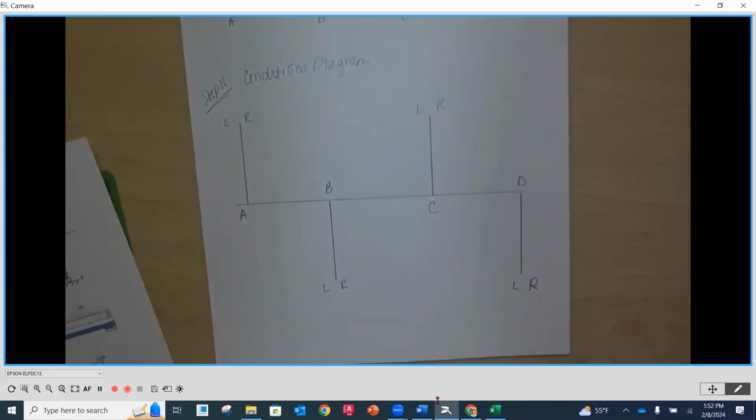So now we're going to go through those things that we just created. Number 1, we're going to look in our shear and moment diagrams. We're going to identify where shear and moment is. We're going to look at our torque diagram and see where the torque is. Then we're going to look back at our arrangement that we made on how we're planning to locate and transmit the torque and the rotational speed, and see what KT factors are present in each one of these locations. Okay. So first things first, we're going to look